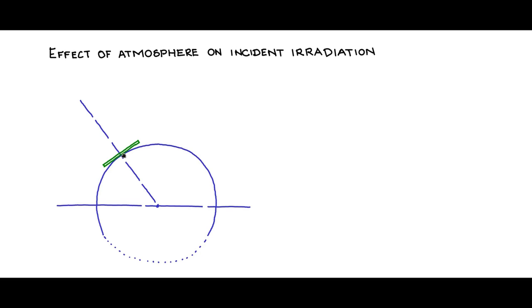Now we have been estimating the energy that is falling on this flat plate collector, and all this time we have been doing that without considering any atmospheric effects, and therefore the incident energy here would be same as the extraterrestrial energy, which is significantly higher than with the effects of atmosphere coming into picture, because the atmosphere significantly absorbs a major portion of the incident energy.